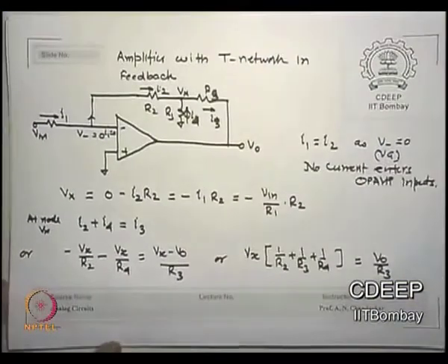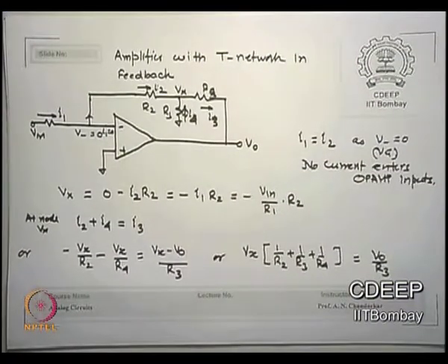You should not come close to Ri. Is that clear? So in some way, if you want to improve gain, you will require R2 to be higher, but you don't want R2 to be too high. Is that correct? So what do I do? Here is the solution. Okay. You replace your R2 by a T network. Is that clear to you?